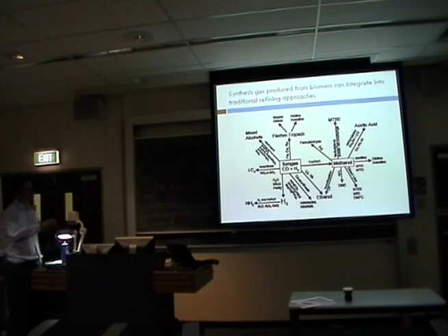So you can react it over a metal catalyst. It would typically probably be an iron-based catalyst for the syngas composition that you get from biomass in order to make what's called Fischer-Tropsch liquids. And so this would actually primarily be diesel fuel, although you can also make olefins and gasoline. This is basically polymerizing carbon monoxide, making water as the byproduct. So you pull off the oxygen and polymerize the carbon and add hydrogen to it. Okay, so Fischer-Tropsch processing is one thing you can do from syngas.